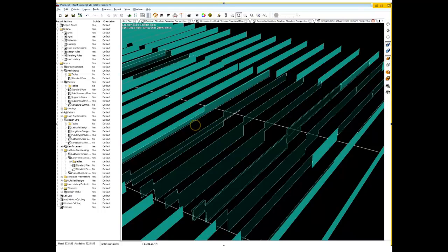What happens with the cross-section slope limit is it's going to compare the two cross-sections one from the other, and it doesn't want the forces to flow in a very angular way. Forces naturally flow along a more gentle slope. So it's going to kind of change or trim back the soffit and surface of the slab to allow a more gentle slope between these angular areas. It's also going to give you more concrete section than in the cross sections that you view.